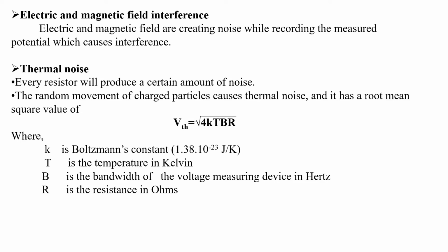So the value for the thermal noise is given here: Vth is equal to the square root of 4kTBR, where k is the Boltzmann constant, T is the temperature, B is the bandwidth of the voltage measuring device in hertz, and R is the resistance in ohms.